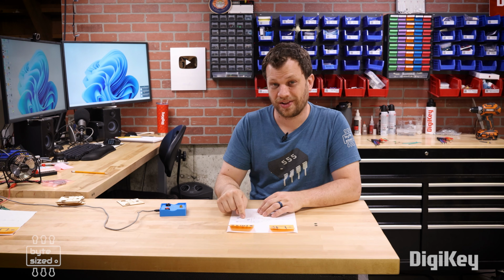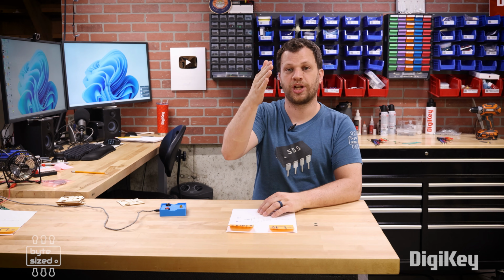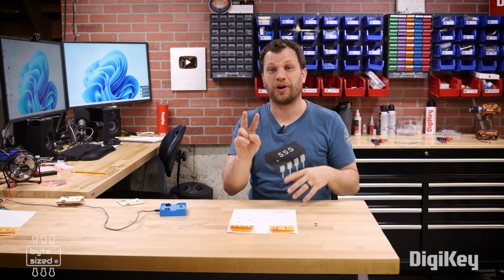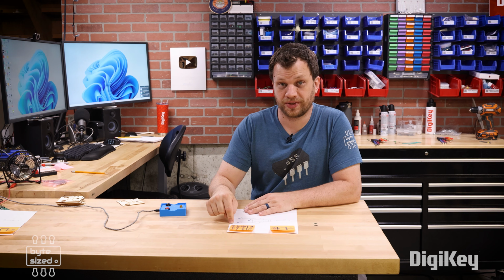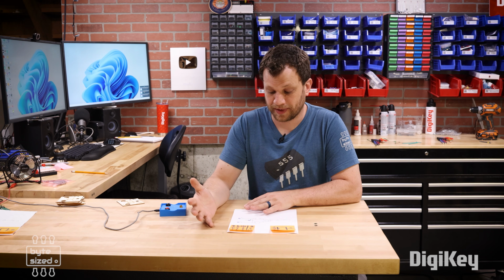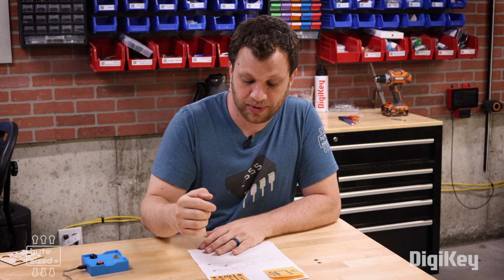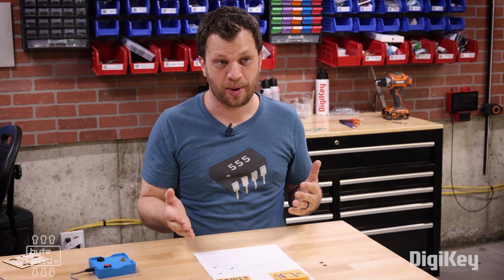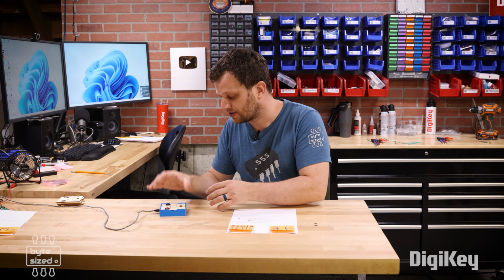We also still have a clock input, and we're only looking for changes on the rising edge, but now instead of just one input, we've got two inputs called J and K. And if you can tell me what those stand for, I would really appreciate it. The truth table for this one is very similar to the D flip-flop, except now when we have both inputs activated, we can toggle the output.